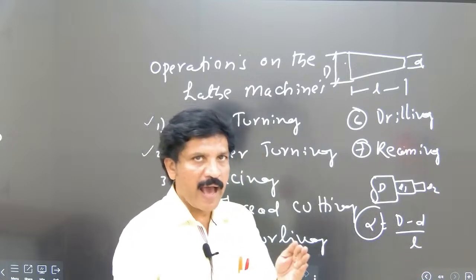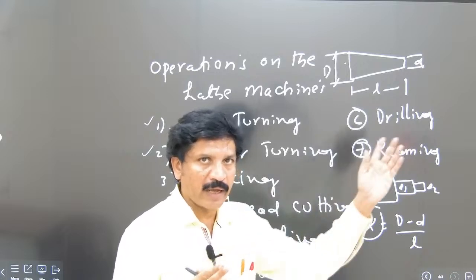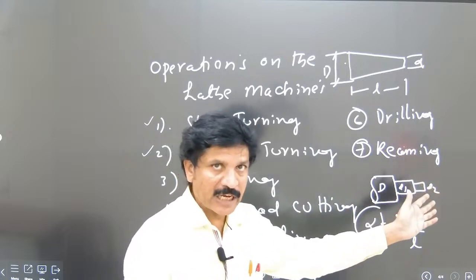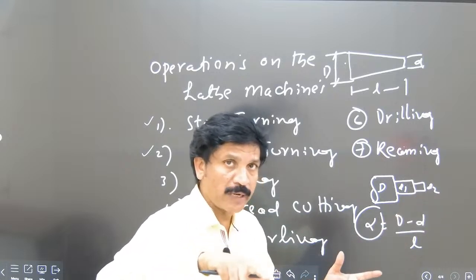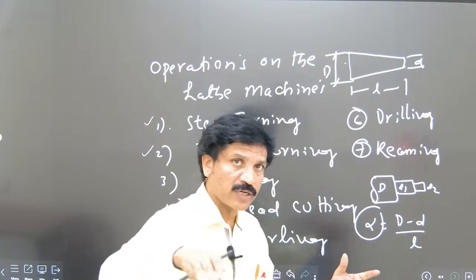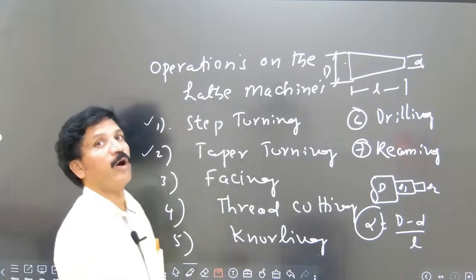As per that angle I can set the tool post inclination, then it is automatically fed and the operation is carried out. That operation is called the taper turning operation.